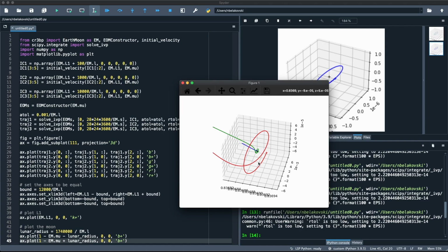So what we're going to do is, as we integrate the trajectory, we're going to look at our position along this trajectory, and we're going to use this initial velocity function to figure out, okay, if this is our current xy position, what does our velocity have to be on a trajectory that excites this oscillatory mode? And then we'll look at how that compares to the velocity that we actually have, and that'll allow us to compute a delta v, essentially.